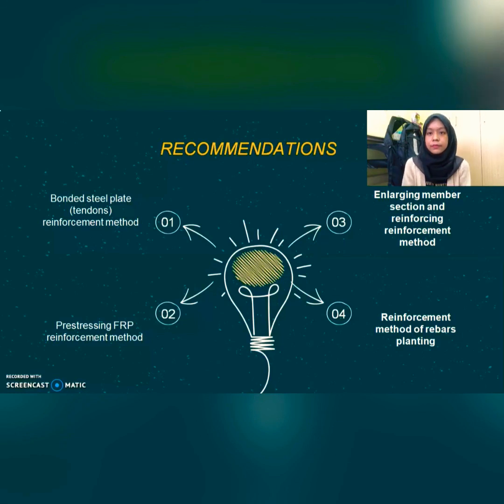engineering costs. Third, enlarging the member section and reinforcing the reinforcement method. When the strength, stiffness, stability, and crack resistance of the beam are not enough, the reinforcement method can usually be used to increase the section of the member and increase the reinforcement. The enlargement of the concrete cross-section can be adopted as follows. Thickening the bridge panel, then increasing the height and width of the beam rib of the main beam. The main point of construction of the main reinforcement bar method is reinforcement of the main steel reinforcement, connecting long stirrups and restoring the concrete protection layer.